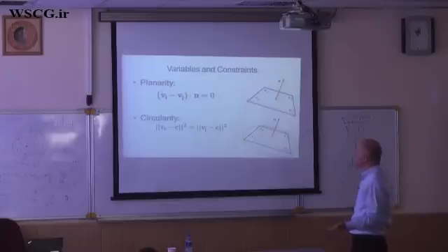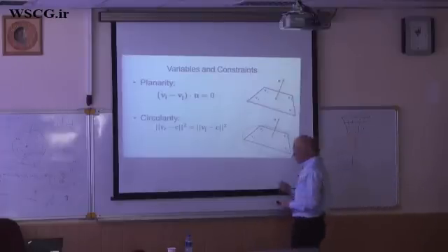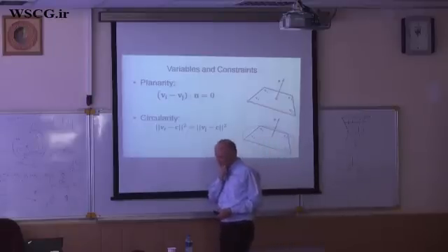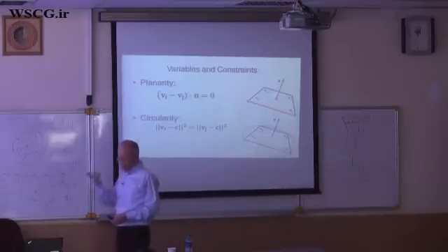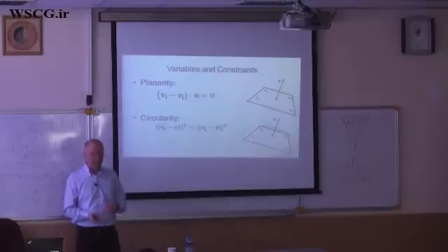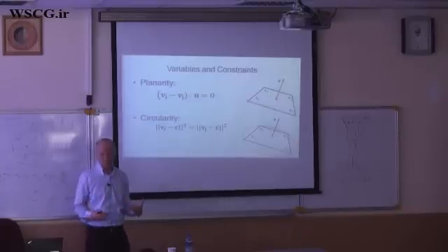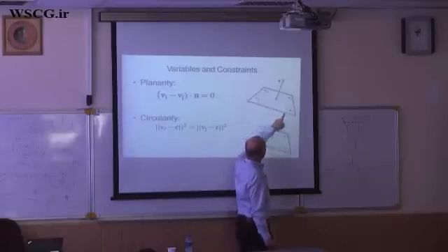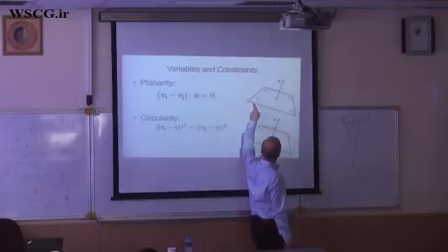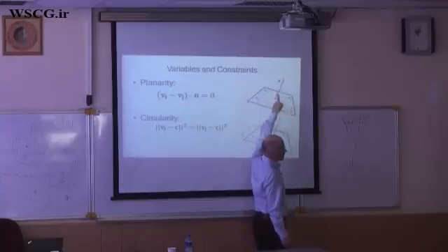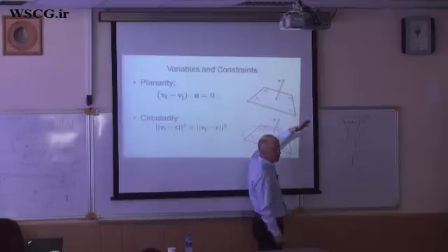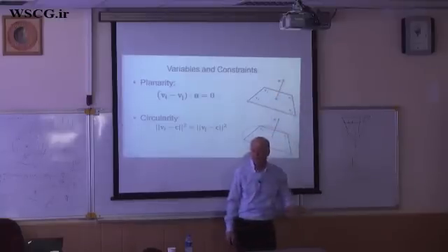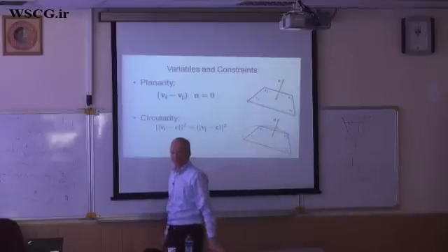More constraints. And another thing which is important, in some numerical optimization techniques subject to constraints, it is bad if you have constraints which are dependent. But here it does not matter. For the quad, if we just require that 3 edges are orthogonal to this normal, right angle with the normal, the 4th edge, of course, automatically is orthogonal.